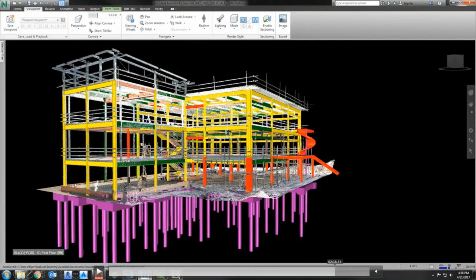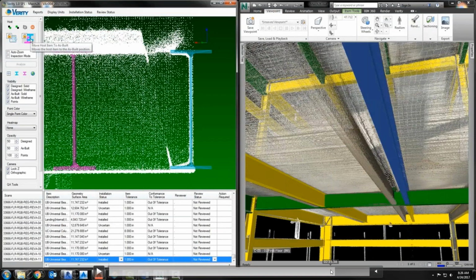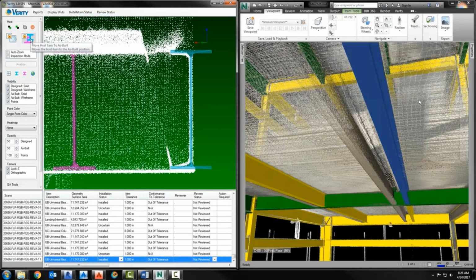I'm going to go back there so you can gauge it again, because maybe you're not getting what I'm saying. As you can see on the screen, this is where, according to your design model or your BIM model, the beam should be. But after the building was constructed, you can see that the beam position is actually more to the left. It's shifted a bit. There can be various reasons behind that. But now for your as-built model, the model that you need to hand over to a facilities manager or to someone as a deliverable, you need to make sure that this design model has an accurate representation of what has been constructed on site. So you would need to move that beam to this point cloud location, right?